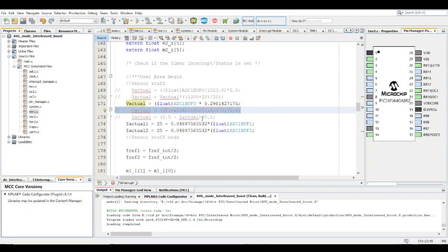And then after that, you want to take that particular voltage and convert that to the actual current, or in this case, the actual voltage. So here you have to scale it back up in the code according to your resistor divider. So in this case, this is 1.2 megaohm, 20 kilo ohms, right? But in this case, because it's 100 millivolts per amp and the offset is 2.5 volts, you have to say 2.5 volts minus the actual current.